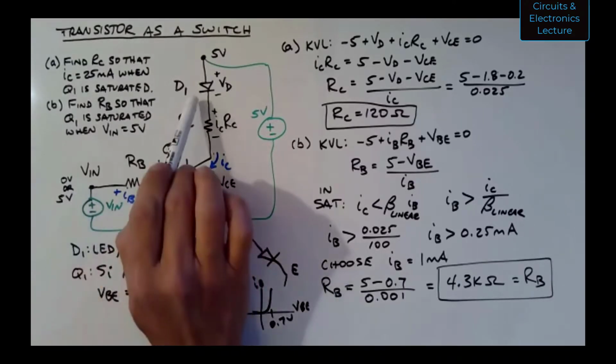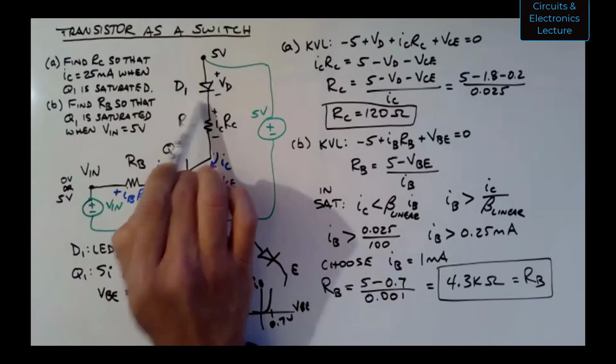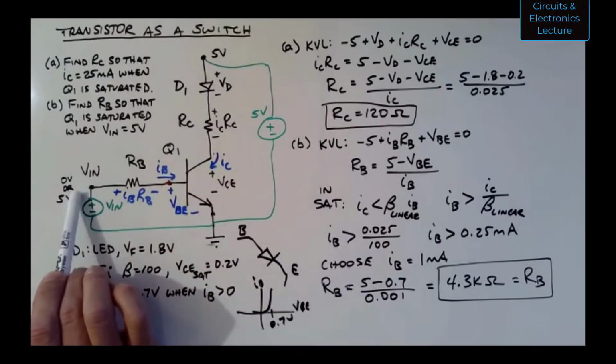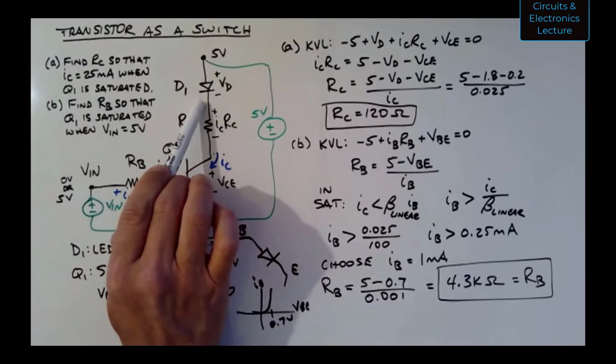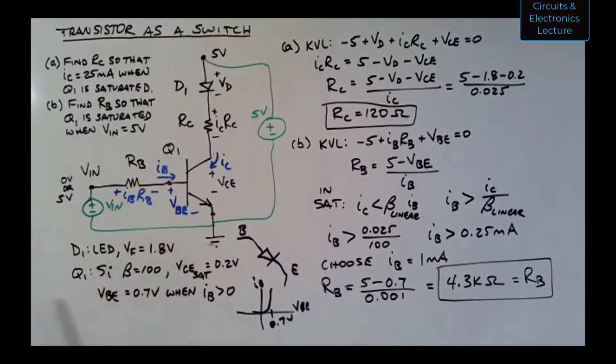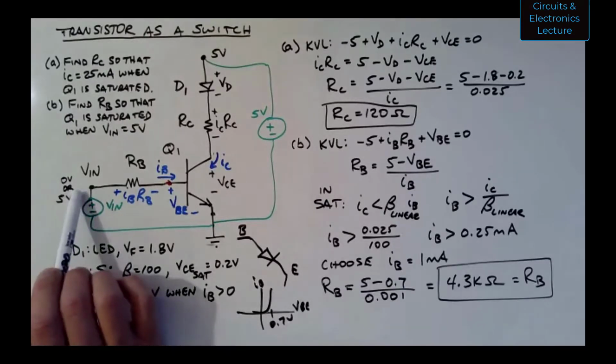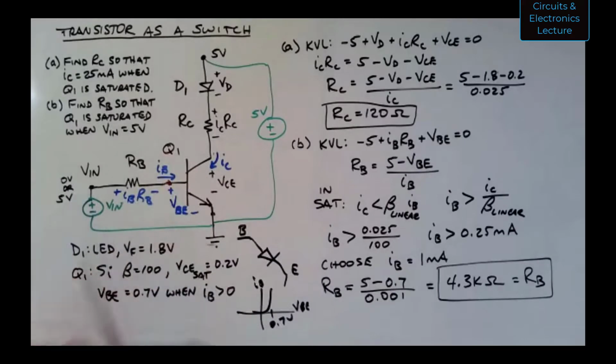You could pulse width modulate the current through that diode by changing the duty cycle of maybe a 1 kilohertz square wave, to control the brightness of that LED. It's like your Petzl or whatever headlamp that's LED. You could control the brightness with the duty cycle. That's what your headlamp does.